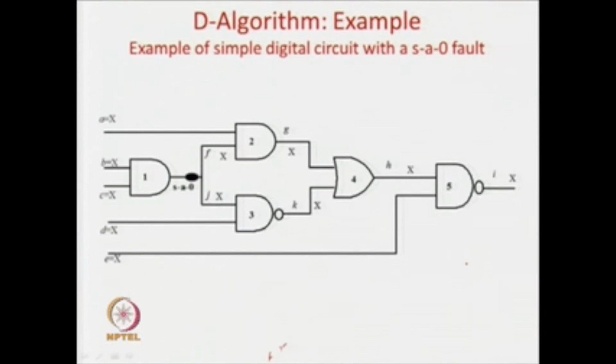So for the D algorithm, life is not very green here, because there are a lot of options and you may be prone to take a wrong option and then again you have to backtrack. The number of faults which cannot be tested is not very high, but in that case you have to try many options and you will fail. But that is not the killing point. The killing point is that for the successful cases, about 99.9% of faults will be testable in a circuit. For all the successful cases, there are still a lot of options available, and it is the duty of the algorithm.